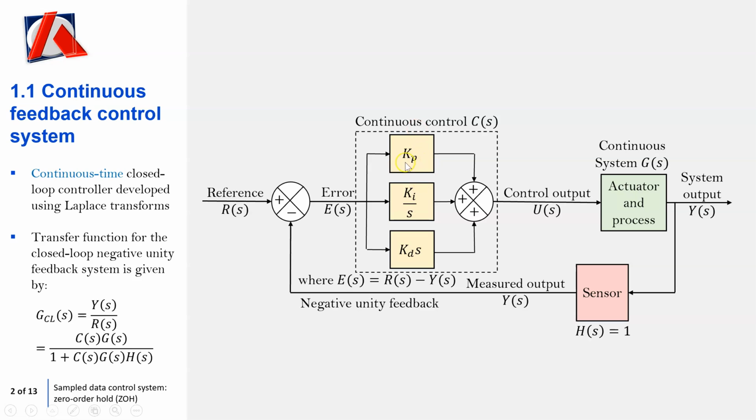So here you've just got your proportional control gain, Kp, your integral, which is Ki, multiplied by 1 over s, so that's effectively your integrator, and s, where s is effectively your rate of change, so your derivative. And then that multiplies by Kd. So if you remember back to continuous time, that's pretty much your form.